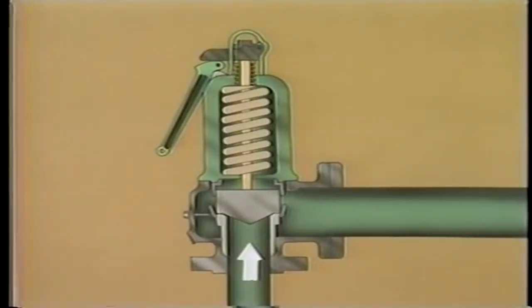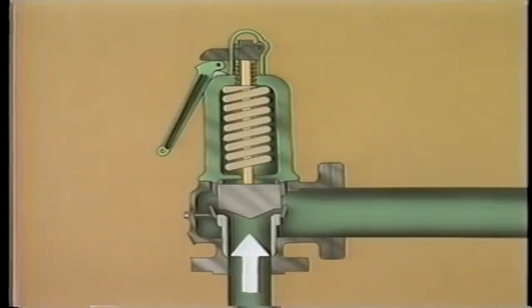If, however, the pressure at the valve inlet increases and exceeds the designated value, the increased pressure will push the disc off its seat. When this happens, pressure is exerted across a larger area of the disc, causing the valve to rapidly move to the open position. This is known as a safety valve lift or popping a safety valve. When a safety valve lifts, pressure is released through the outlet line, which is usually vented to atmosphere.